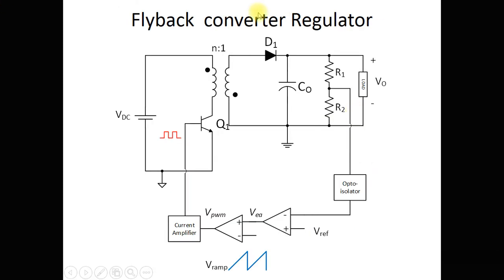This is the flyback converter regulator. Now again, we'll be interested in having the regulation. So the feedback and the regulation part is exactly like the one which we have seen earlier in the case of the other converters. Necessarily this gives you isolation. At the same time, you can see the grounds are different here, so this signifies the isolation. And we have the feedback.